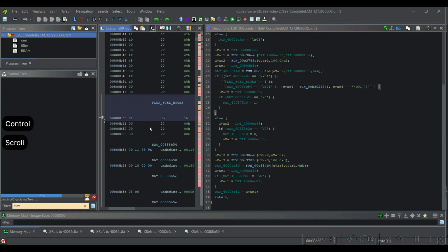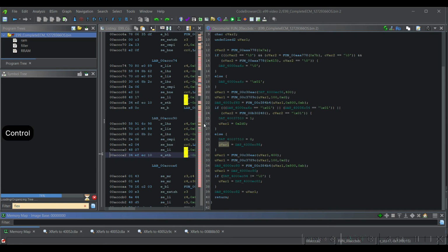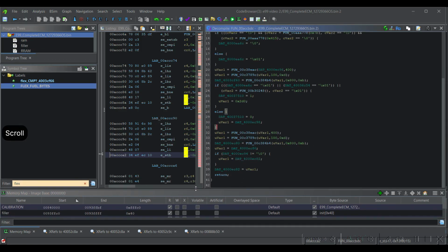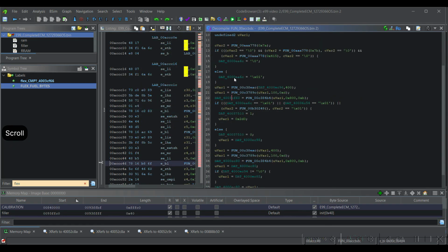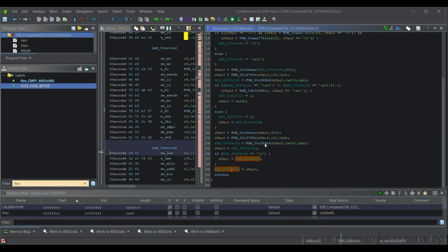Oh, it might be an offset. It might be one of the other bytes in this function. That could totally be it. Yeah, that could be it. Okay. Well, regardless, that's set back to the proper value. So I would go ahead and start tracking down, like this RAM address right here is probably going to be used in the x-axis of a map. Yeah, you're going to have to start just tracking these throughout the ECU and try to find the closest map, I guess.